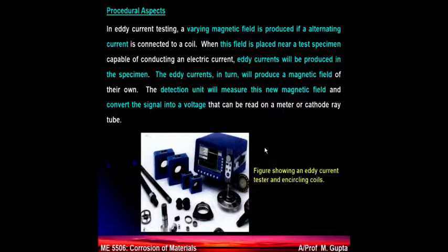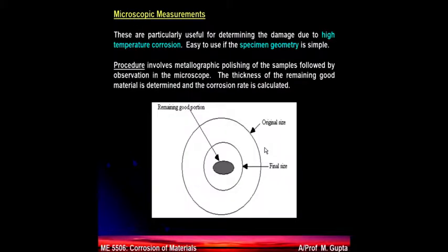Used in many applications, but for thickness measurement of the wall, I think the ultrasonic method is more popular than this method. Then you have microscopic measurement, applicable only for situations where you can take a bit of sample, you can cut a sample out and examine it.